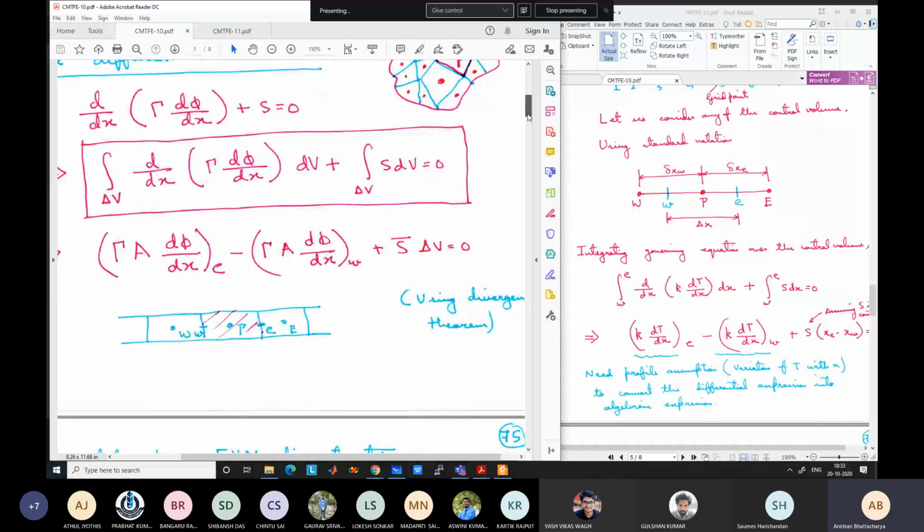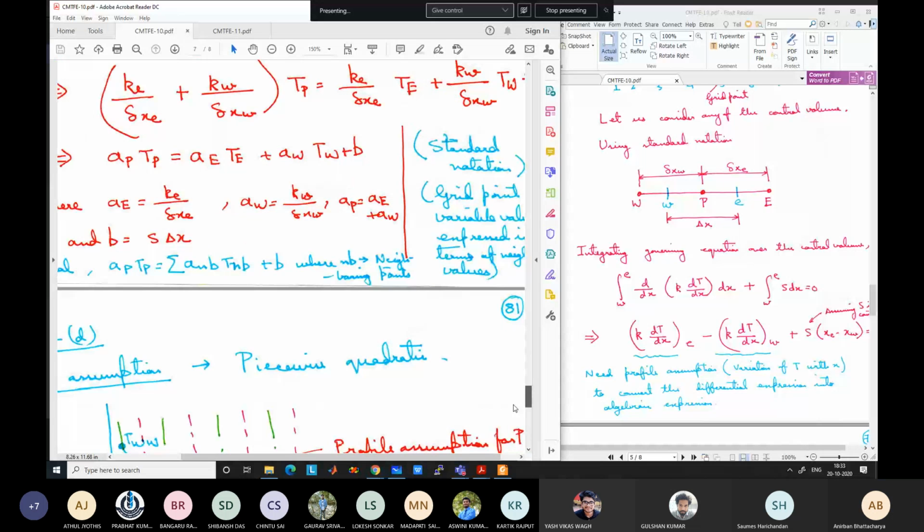Okay, now I remember. So what your CFD software is doing when it is meshing, it is showing you a nice mesh, but actually it is not storing any of the lines and other things. It is creating a number of control volumes, meaning it is generating the index of the control volumes. So this is 1, 2, 3, 4, 5, 6, 7, 8, even if it is irregular, so 9, 10 like this.